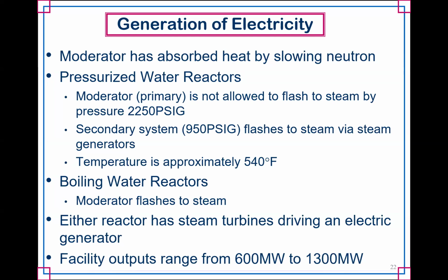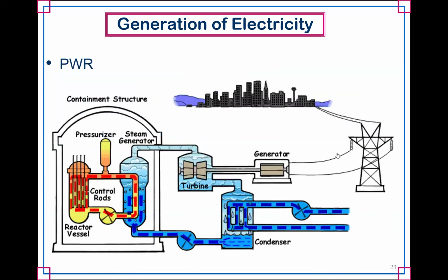So the steam turbine runs at 1800 RPM, 3600 RPM, whatever you desire. That's typical speeds that you would see. And then the rotation of that generator, so you have wires and a magnetic field inside of another set of wires, and you've got a changing magnetic field that's cut by a closed loop, and then you produce electricity. Typical sizes, 1600 megawatts to 1300 megawatts. Again, this is in the US primarily.